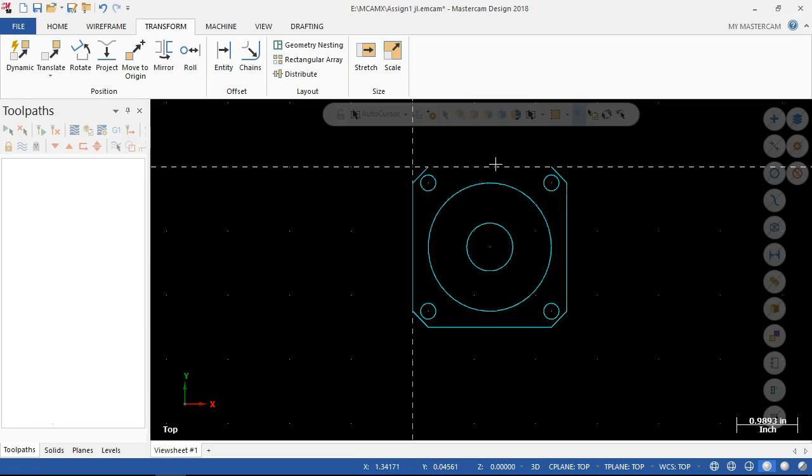And then my material thickness is varying between 15 and 20 thousandths oversized. So I'm at the bare minimum of that 10 thousandths that I want to take for cleanup. Right, so we're juggling those numbers at the control so that if I see a trend that material is not cleaning up all the way around or on one side, at the control we can move it back a couple thousandths, try and bring it back. Or we're over at the sanding block and the Scotch-Brite making it look pretty and it's still within tolerance, get it out of here. No, nobody ever does that. All right, so that gives you kind of the basis.